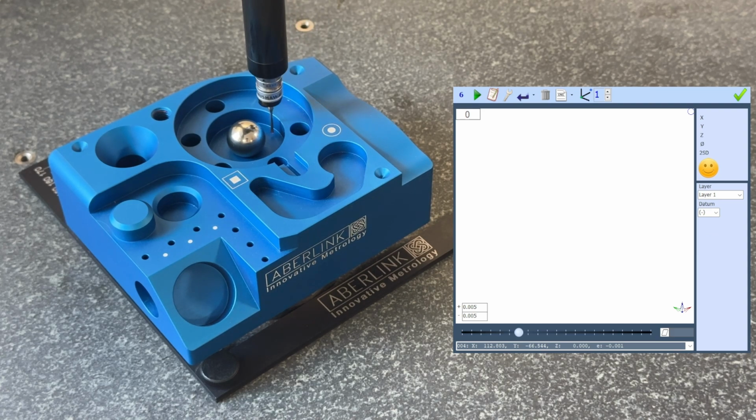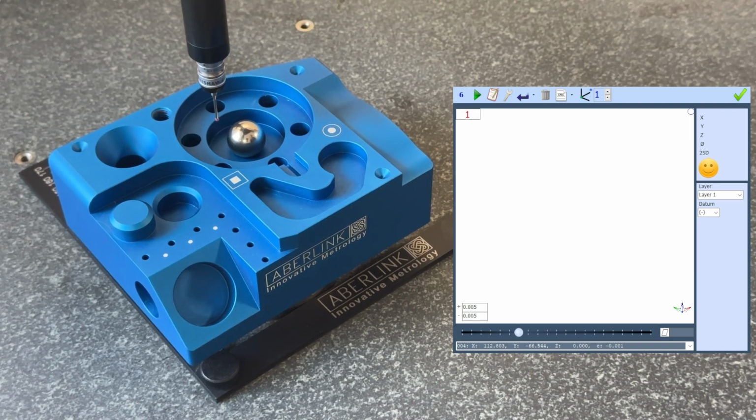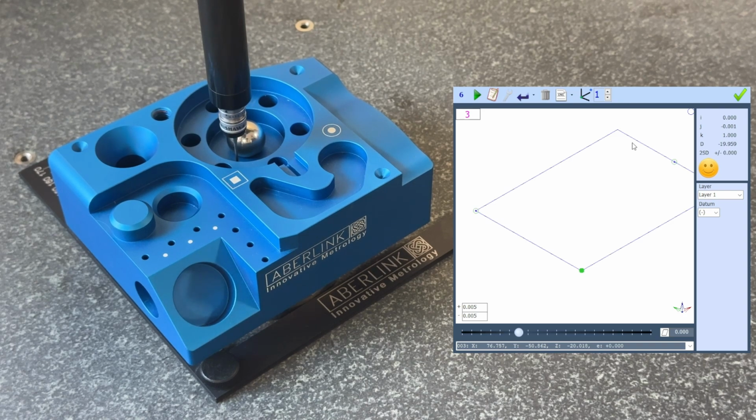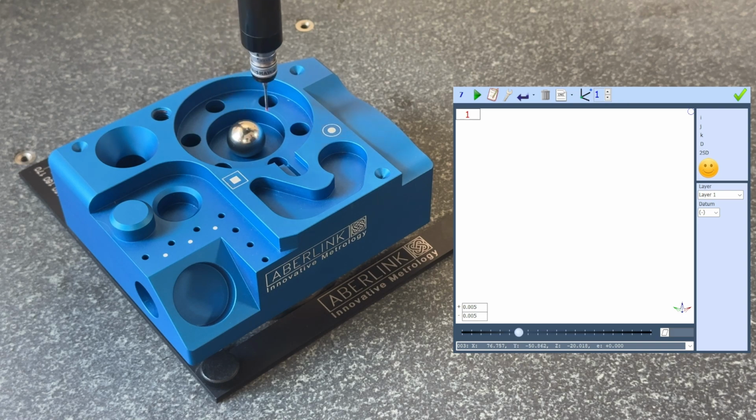2 planes, and to do this I'm just going to define 3 points, one on the sort of outer edge. Imagine these like a triangle. There we go, hit the green tick. Another plane slightly closer in. Again, like a triangle, as that will define the 3 points required for the circular path that I will modify.